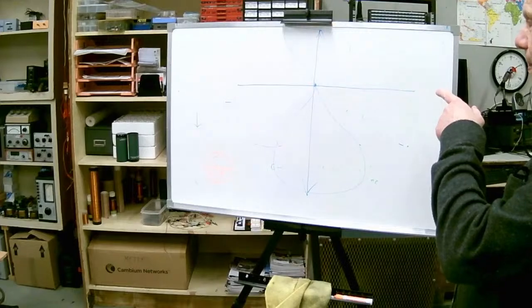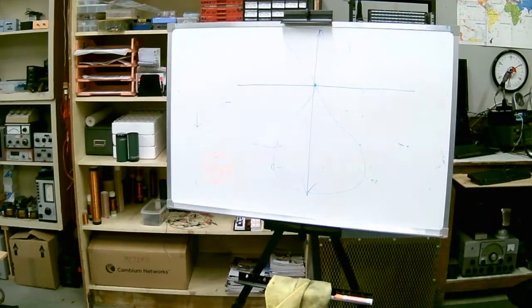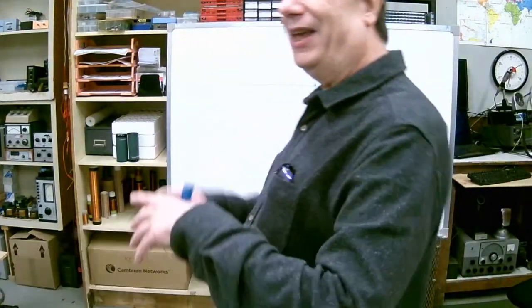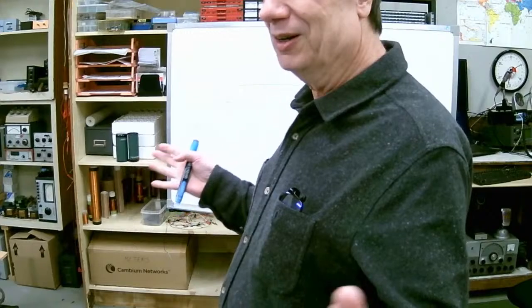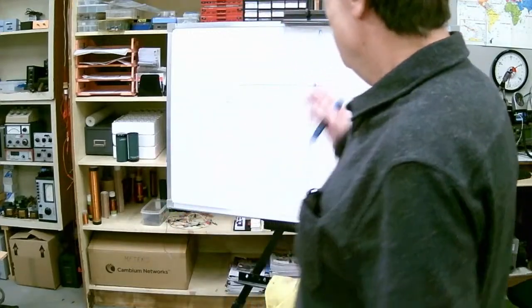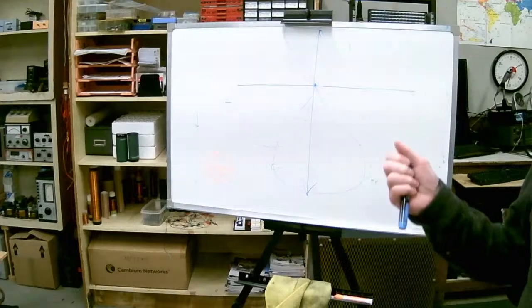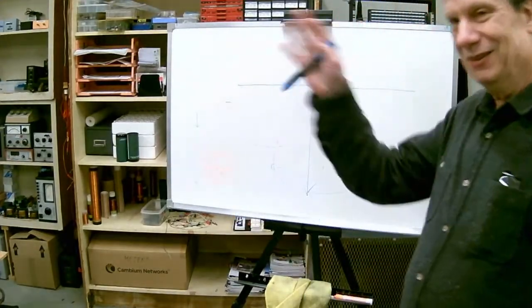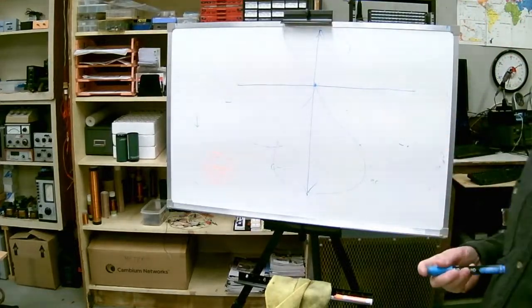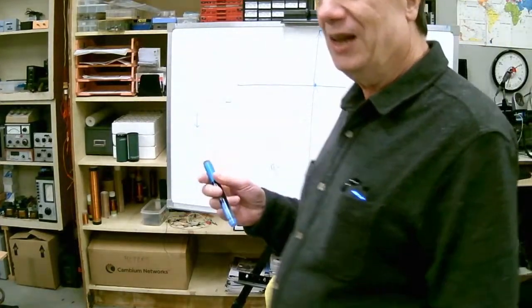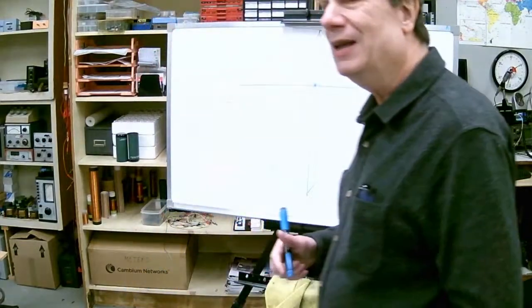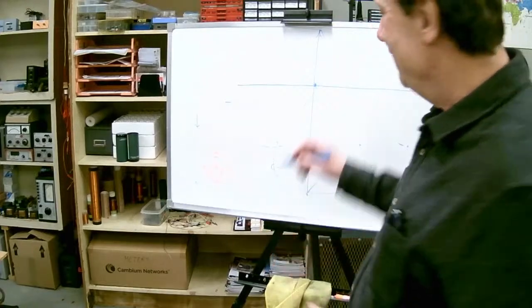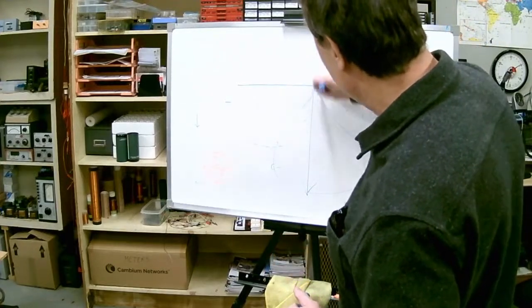Now, a radio signal attenuates as it goes over distance. We talked about decaying sine waves where you have resistance in the circuit and it goes away eventually. A radio signal in free space, in outer space where there's nothing to use up any energy, is still going to attenuate, and that's called geometric attenuation. This thing is not a laser beam shooting all the rays parallel to each other.